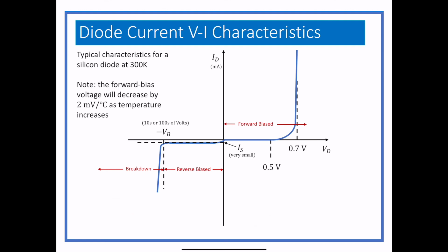Yes? So when you have devices that range anywhere from like 40 to 60 degrees Celsius, like they change that much, how do you typically construct it? Well, that's a huge range. Because you do, but you notice that the change is only 2 millivolts or something. So it's not a huge difference, but depending on the type of device, you can actually find devices that won't be so temperature sensitive. So you basically have to choose the device properly.